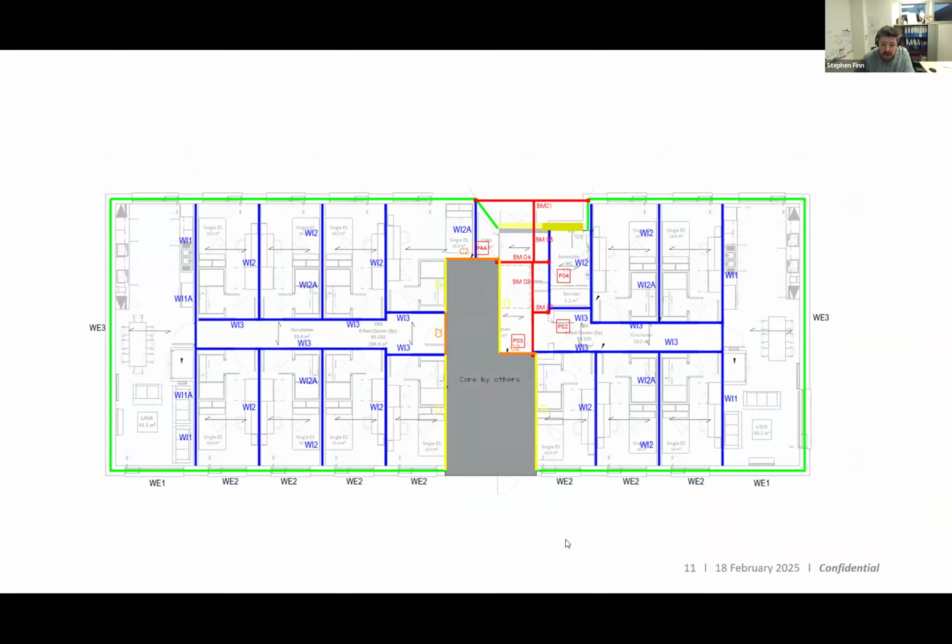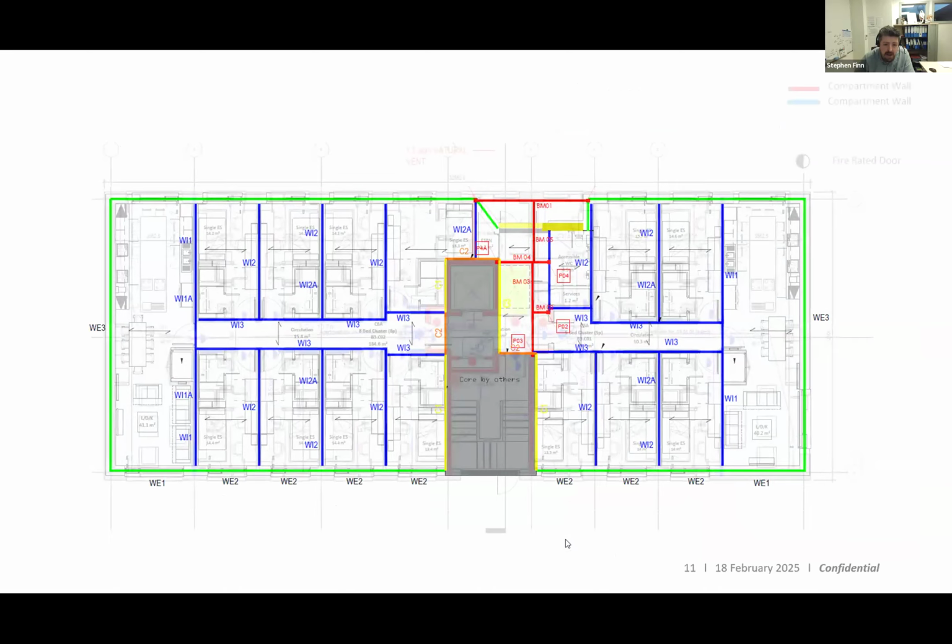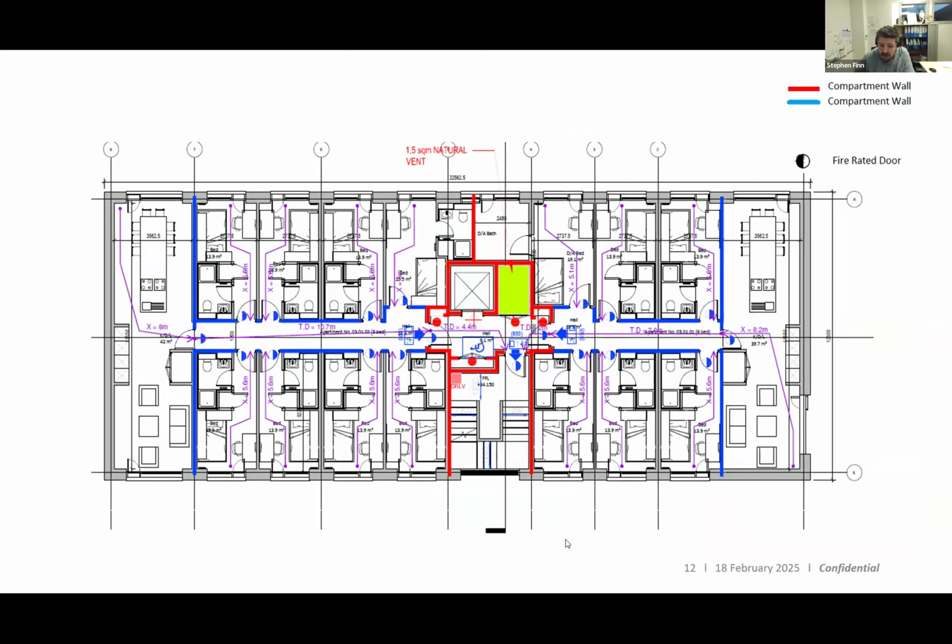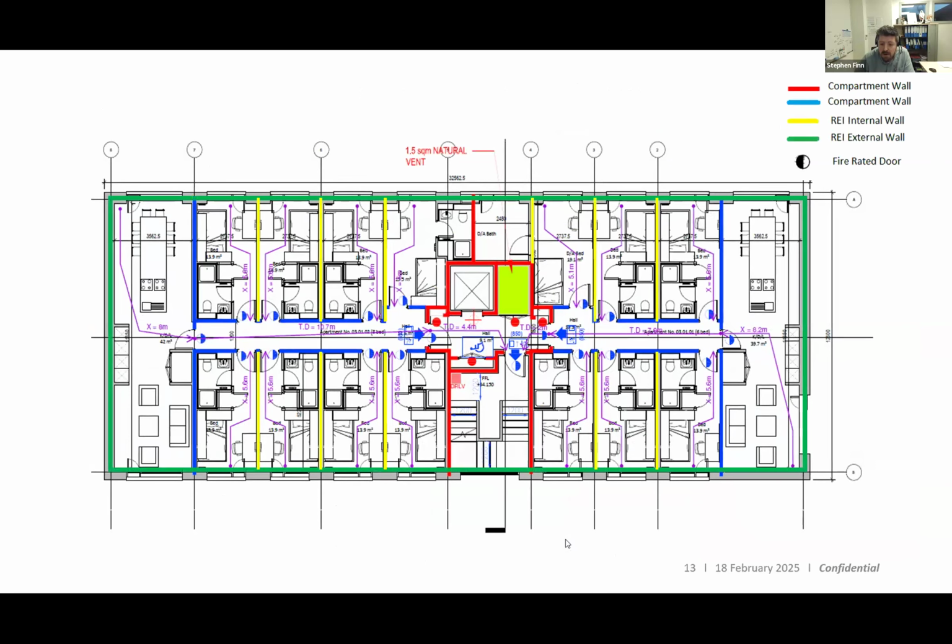And then from that, we take the system information and the tested information from whatever MMC solution is proposed, and we then go work with the fire consultant to take your traditional fire strategy drawing and readjust it and have a more holistic, collaborative approach to our fire strategy drawings, highlighting, I suppose, the load-bearing wall elements for this as an example, 2D LGS structure, highlighting the load-bearing wall requirements and their REI requirements as well.